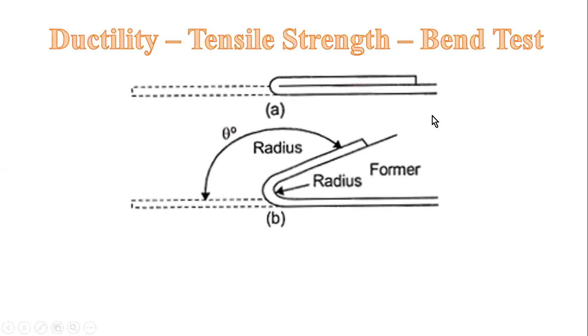The next type of testing in bending is the angle bend test. The material is bent over a former, and the nose radius of the former and the angle of bend are fixed by specification, in any specification that you needed. Again, no allowance is made for spring back. So if you have a piece of metal in here, in which you can make this bend in this radius, and it doesn't deform or it doesn't break, it is approved for the bend test.